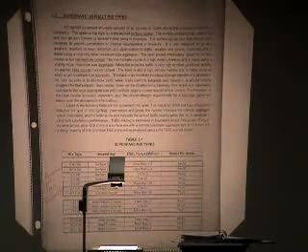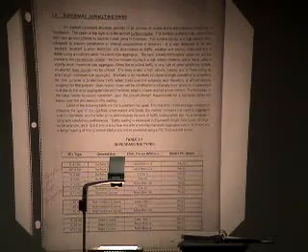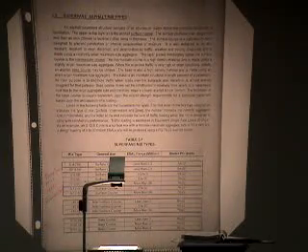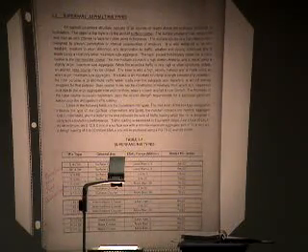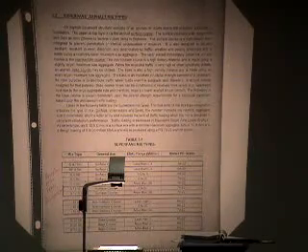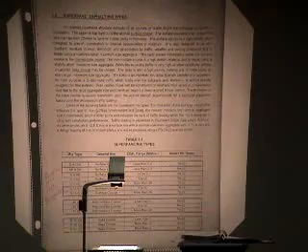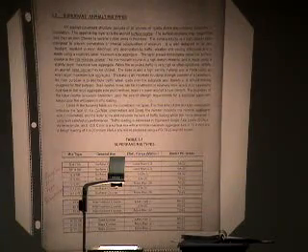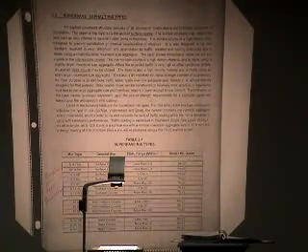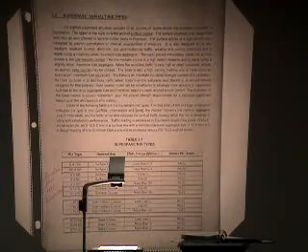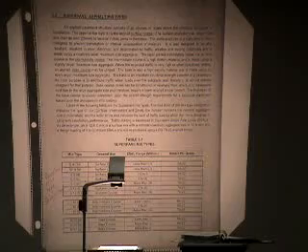As Bob mentioned, it's just an acronym for Superior Performing Asphalt Pavements. There was a common misconception that it was going to solve all the paving problems, but that's not really the basic concept. That's not necessarily true. The Superpave specifications were set up to be a performance graded system. That's how they came up with the PG gradings on the asphalt binder.